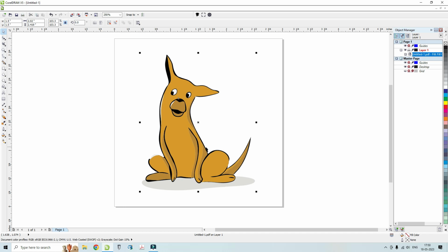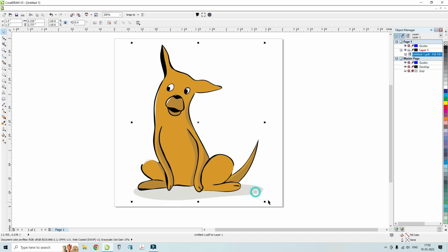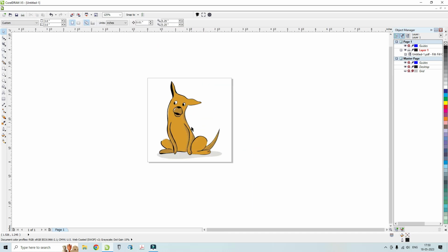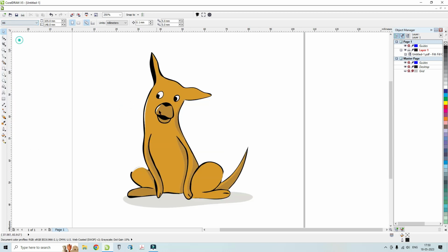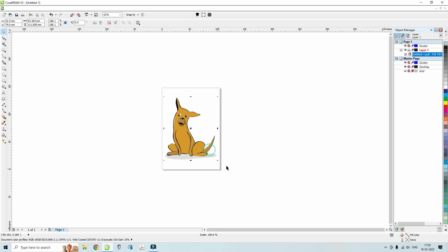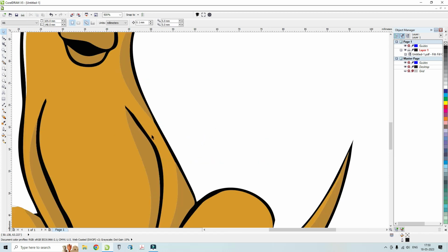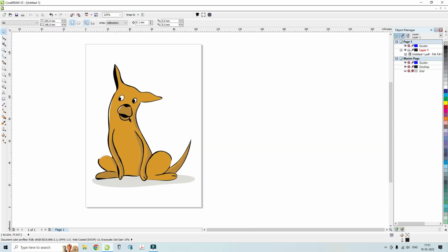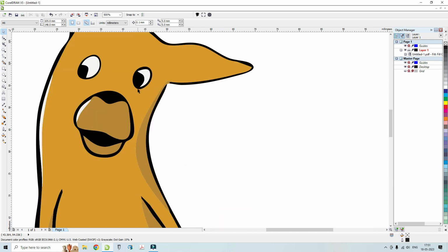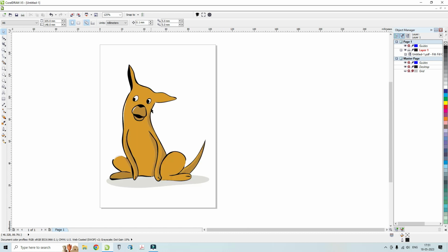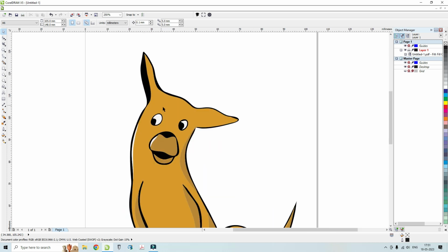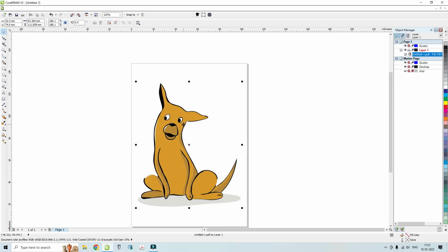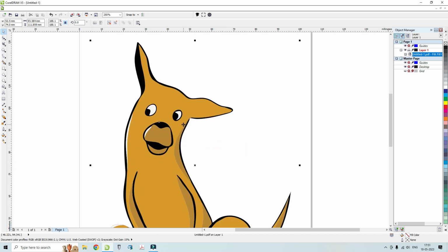It does not basically matter what canvas size you design in, in case of CorelDRAW or Illustrator, but at the same time, if you are using a bitmap or an image in addition to this vector artwork, you have to remember to go for the largest canvas size available, as big as possible, that your system or your software can support.